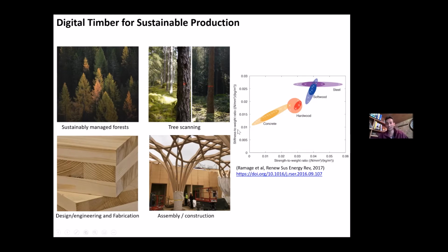One of the advantages of natural materials is their lightweight, particularly in comparison to their stiffness and strength. And in the case of wind turbine applications, both the tower and the blade are facing quite a lot of cantilevering loads, so it's bending loads, and therefore stiffness to the power of a third over rho is an important material performance index that you would want to optimize.